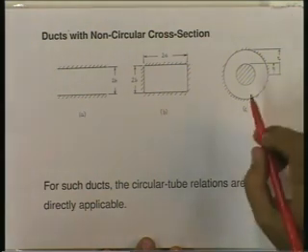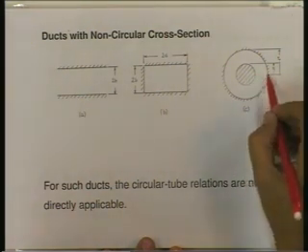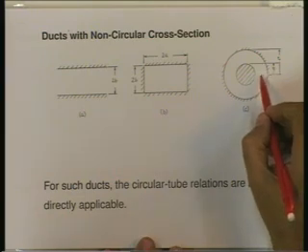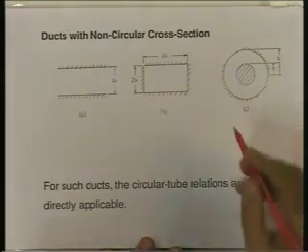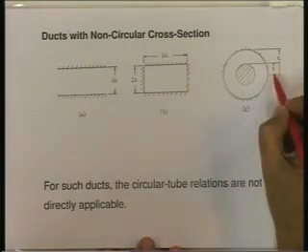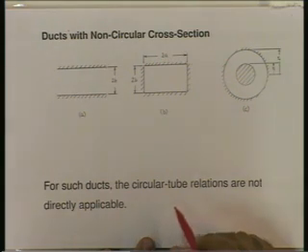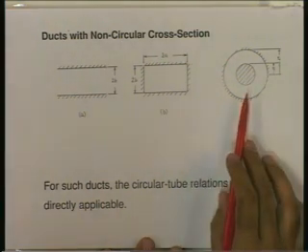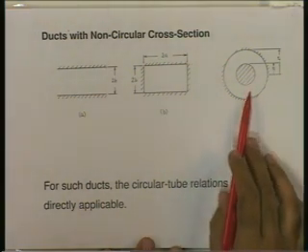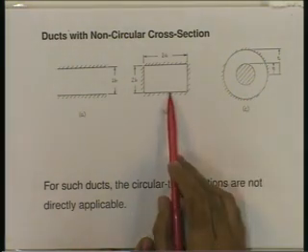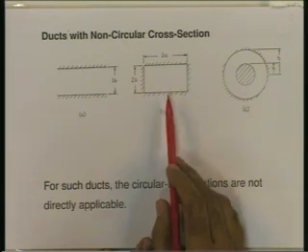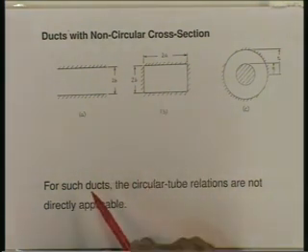So, it is possible that this is a tube inside another tube and this is the annular zone of flow. The inner tube will have a radius Ri, the outer tube will have a radius Ro. This is a common situation in double pipe heat exchangers, and this is an approximation of a situation which is reasonably common in car radiators.